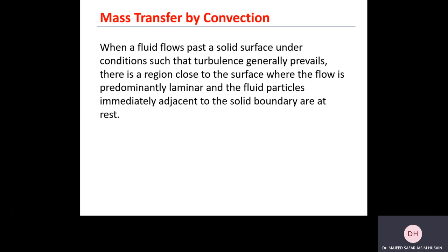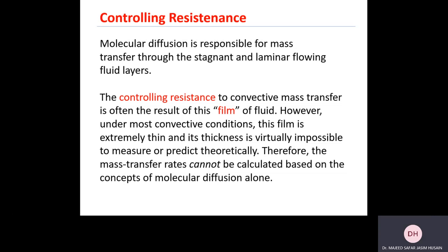It is a similar approach. So the area next to the surface is laminar, and it's controlled by diffusion. Molecular diffusion, in that case, is responsible for mass transfer through the stagnant and laminar flowing fluid layers.